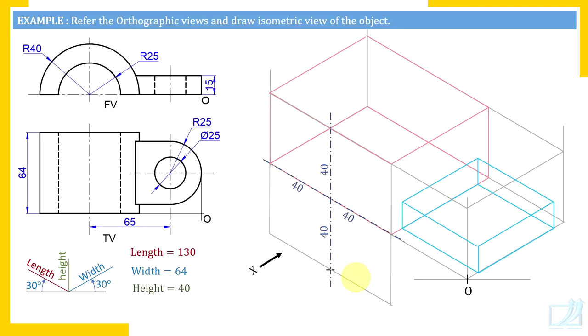And complete the rhombus. Now draw longer diagonal and shorter diagonal. So longer diagonal and shorter diagonal. Now try to understand. I have explained you in that isocircle video that isocircle in manual drawing is a combination of 4 circular arcs, 2 longer arcs in this wider quadrants. Check the quadrants formed by these center lines. In the wider quadrants, you get longer arcs, and in other 2 quadrants you get shorter arcs.